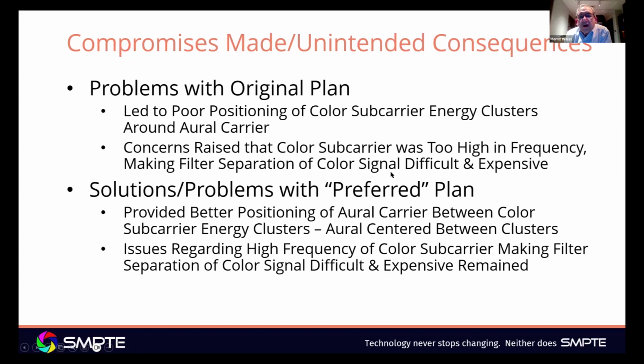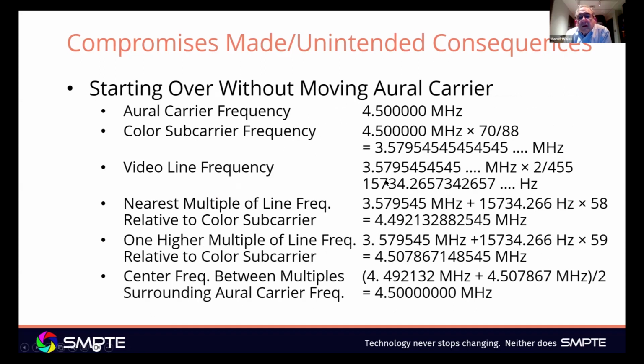We moved the line frequency by 1.001. And since the line frequency is locked to the frame frequency by a factor of 2/525, that forces the frame rate to be off by that same 1.001 factor. And so you can see how that propagates through the whole system, and it probably would deserve another page, but I didn't get there.